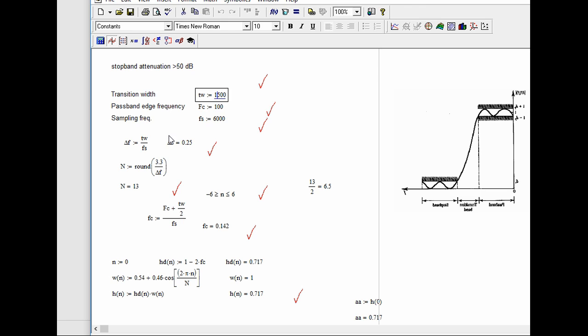So by now hopefully you could have done all this on a piece of paper, and then our cutoff frequency, we take that 100, we say plus that divided by 2. Make sure that you do the plus and the minus the right way. You can't put that on top now, or else it will divide that one by 2 as well. Remember the basic school math rules. Divide by your sample frequency, giving you that new value there.